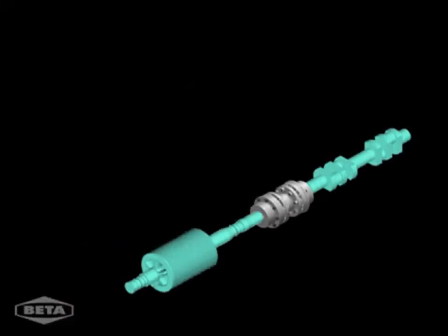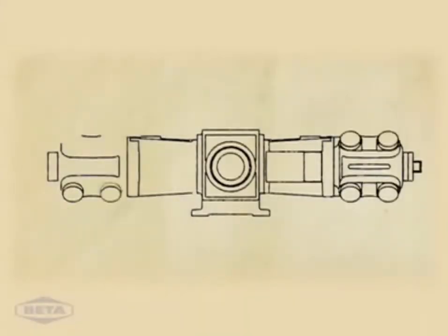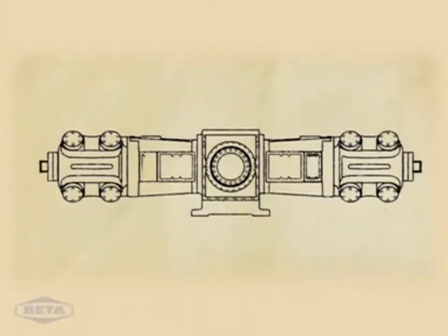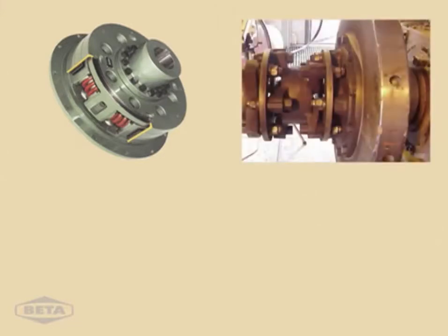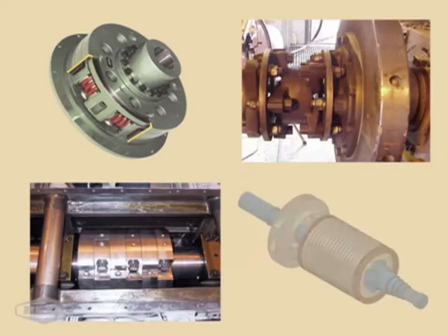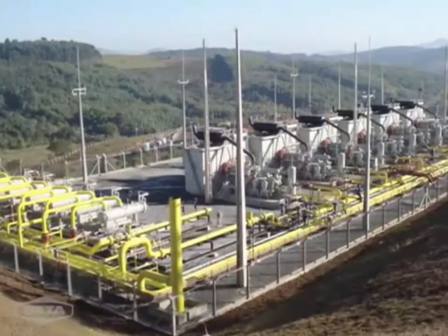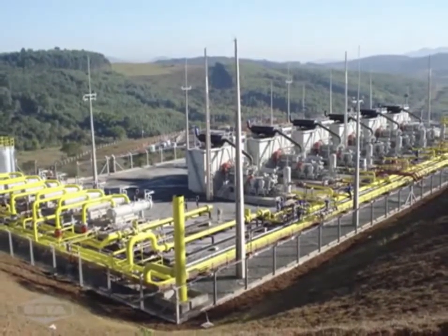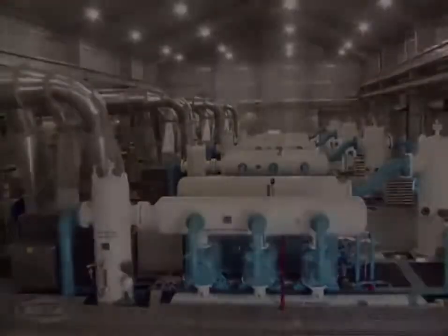The best way to mitigate these failures is to order a torsional vibration analysis before a unit is built. With early involvement, the system can be modified more cost-effectively and easily than later. Changing the coupling size or style, adding a flywheel or a detuner, and changing the shaft material or size are all easily done if the components haven't been built. If the system is already built, then needed modifications are often more expensive and complicated, resulting in delayed delivery of the unit.